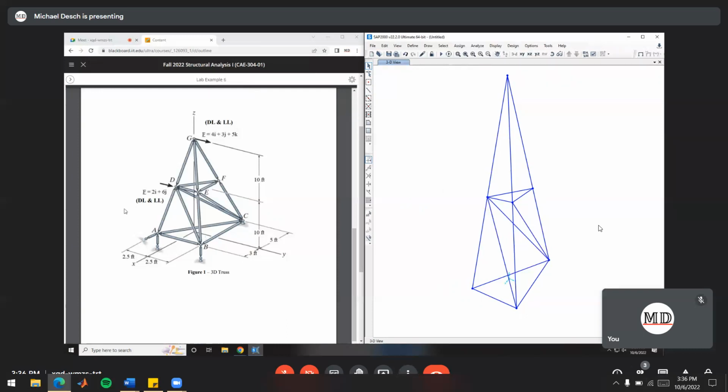I believe the way they drew it here for the textbook is so that it's technically a determinate truss. If you have a 3D pin at each of these joints, it's technically indeterminate to the third degree because there's 3 extra reactions that you don't have equilibrium equations for. But it's the computer, it doesn't care. So it's way easier than figuring out how to model these boundary conditions here. It's doable, just a little out of scope for what I want to teach right now.